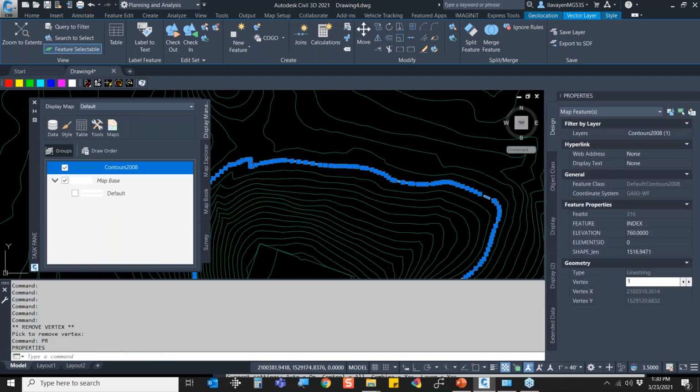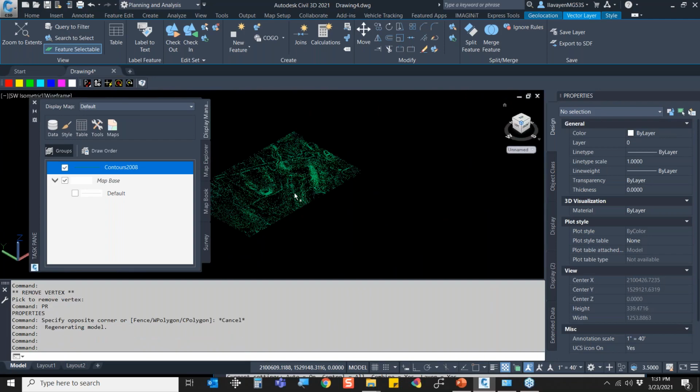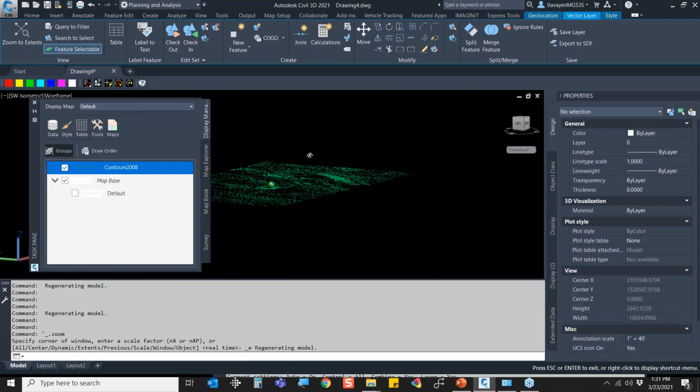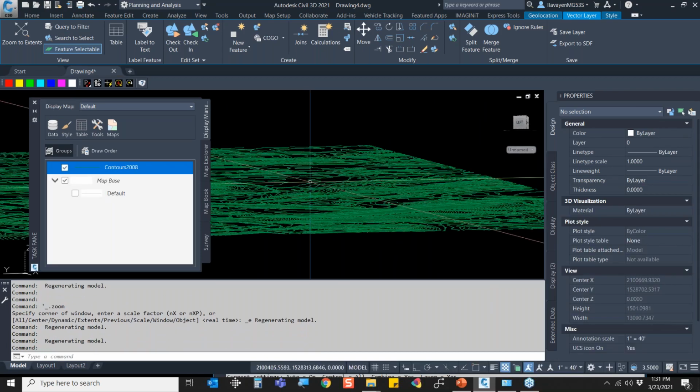And this is going to vary from municipality to municipality. Whoever is hosting this database, what's important is the elevation, this right there. This is all flat. If I try to spin this in 3D, you'll notice that this really doesn't have an elevation to it. It does have embedded intelligent data on it, but these contours are flat. If I try to create a surface from this, it's not going to be possible, even if I did the insert or import option. But there is intelligence here.